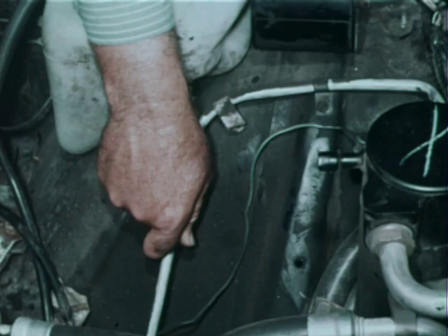With the compressor clutch engaged, feel the liquid refrigerant line on the condenser side of the expansion tube. If it is cold, there is a restriction on the high side of the system, which will require that the system be purged and the restriction repaired. Look for a frost spot on the high pressure lines and condenser to locate the restriction.